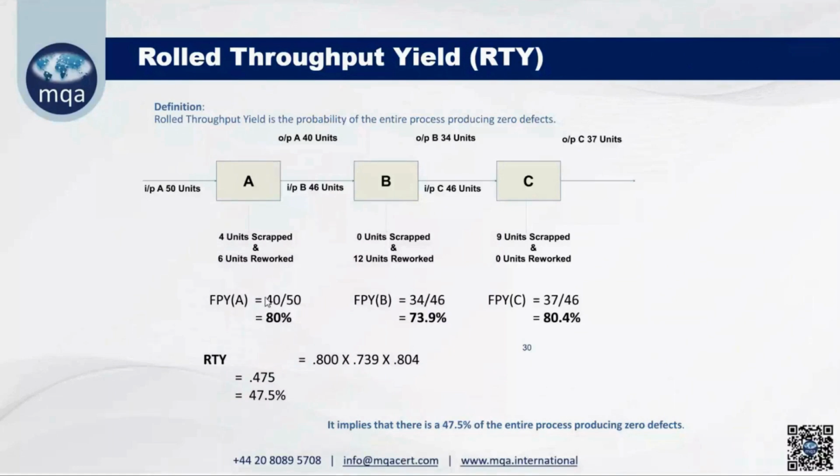We never calculated it in real yield, but we have added them in okay parts. So 46 pieces, 0 scrapped and 12 reworked. So total okay by the machine is 34 out of 46. So 73.9% is the first pass yield for the part B.